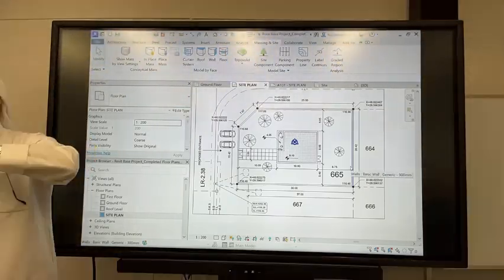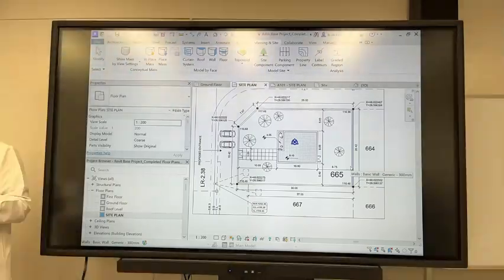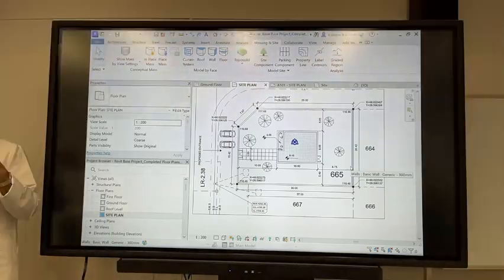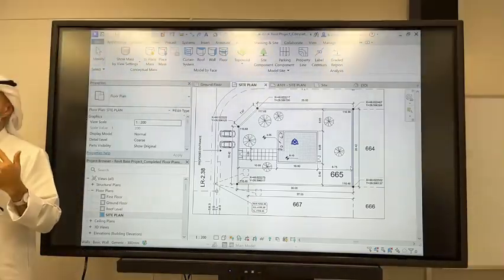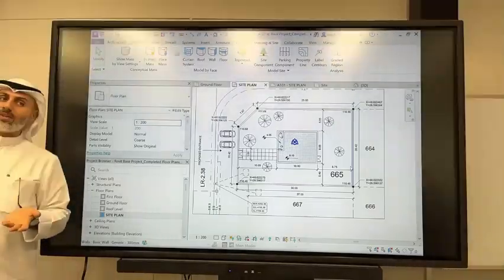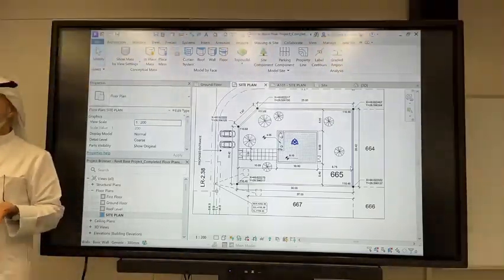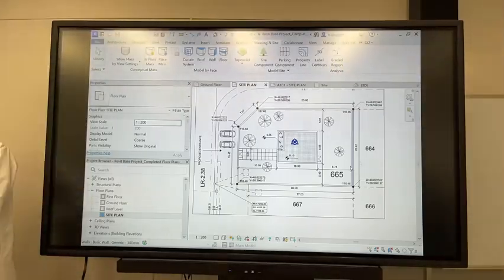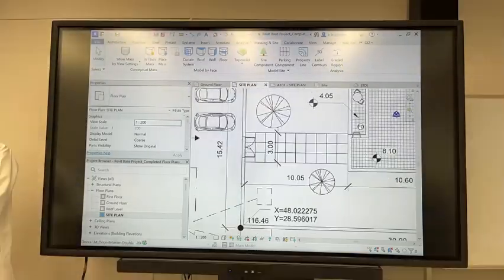If you look at your section, it's plus. So it's sidewalk level. So you draw a wall on the sidewalk level. Unconnected, its height is two meters or a meter 80, a normal fence you draw, and then you can add a door to it, a double door. Okay?